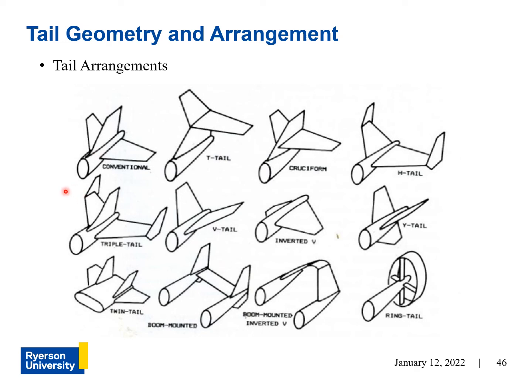And the conventional tail surface provides adequate stability and control, but at the lightest weight, because there's less reinforcement required in the structure, because the connection, or rather the hard points here for each surface is sufficient in securing the tail surfaces and doesn't need additional reinforcement. So therefore there's lighter weight. Now the T-tail is also widely used, but it's heavier than the conventional tail.